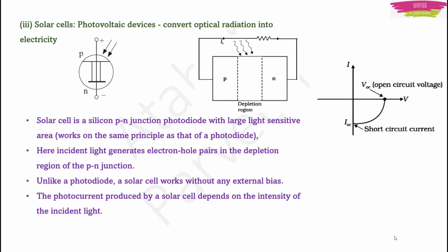Okay. Now what will be the working of this solar cell? Here you can see that we don't know whether it will be forward bias or reverse bias because we are not connecting any battery in the circuit. But then look at the direction of the current. The current outside the junction will go from P to N, isn't it? But what will happen inside the PN junction diode? We know that electrons move from N to P first, right? So the current moves from N to P inside the junction, but outside the junction, current moves from P to N.